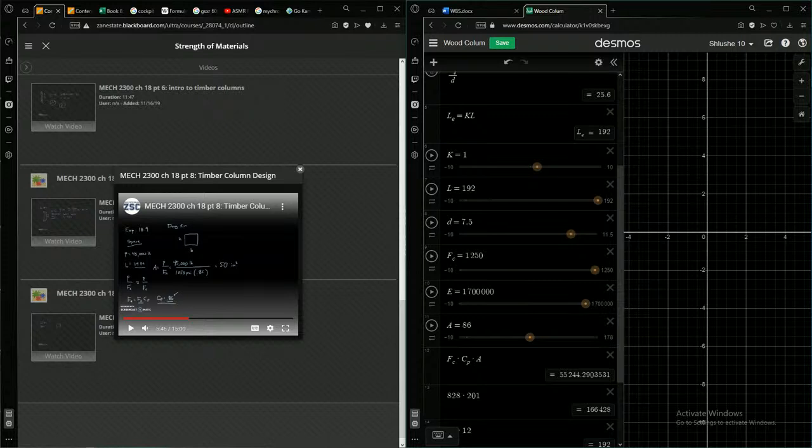So let's see. For a load of 48,000 pounds, the type of square or rectangular beam we're going to need is going to be a... Oops, I didn't take note of what beam it was. It's going to be an 8 by 12. So an 8 by 12 beam. Thank goodness none of these are in metric, because this whole equation system would slightly break, because I'd have to do a lot more converting. This, I could just spit numbers in and I get answers out, which is useful.